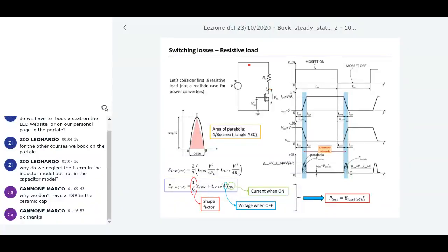So in order to do that, let's consider these simple circuits on the top of the slide, in which you have a power supply V, a constant voltage, and a MOSFET. Here is a low side transistor, so the source is connected to the reference voltage. Then you have the resistance on the drain, RL. This situation is not a realistic case for any practical switch mode converter, okay? But this is a starting point for my discussion.